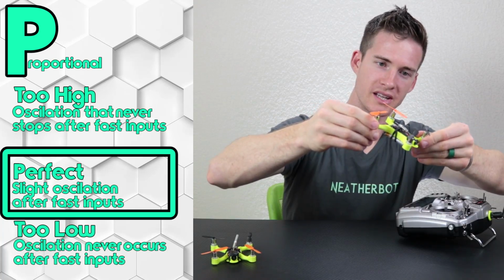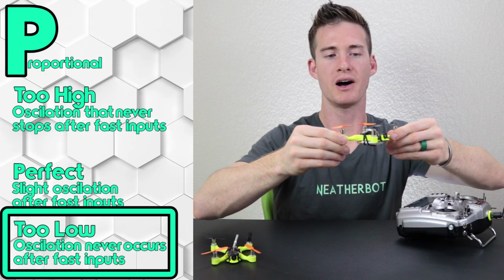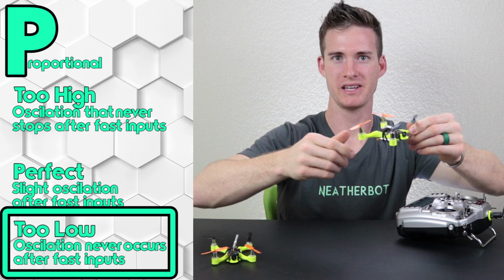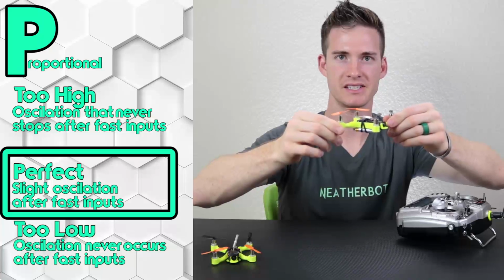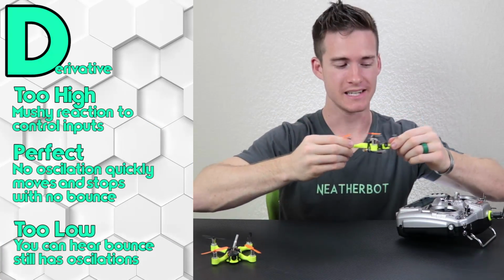If it vibrates for a really long time, you want to keep decreasing P. Also, if it pitches forward and then comes back without vibrating at all, you want to increase P. So you want to be on that edge where it vibrates just a couple oscillations and then levels out and dampens itself. At that point, you're good with P, and you move on to D.